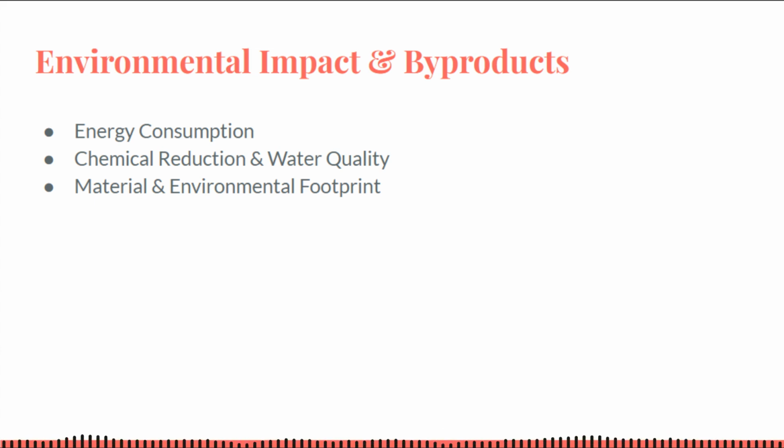Another byproduct consideration: ozone can react with certain contaminants to form innocuous end products. For example, ozone will oxidize ammonia from urine or sweat into nitrate. Over time, nitrates can accumulate slightly, but this is usually managed by periodic water dilution and is far preferable to having ammonia form chloramines. There is a minor possibility of bromate formation if the pool has bromide ions from using bromine or some minerals, and ozone is applied, but in outdoor residential pools, this is typically negligible.